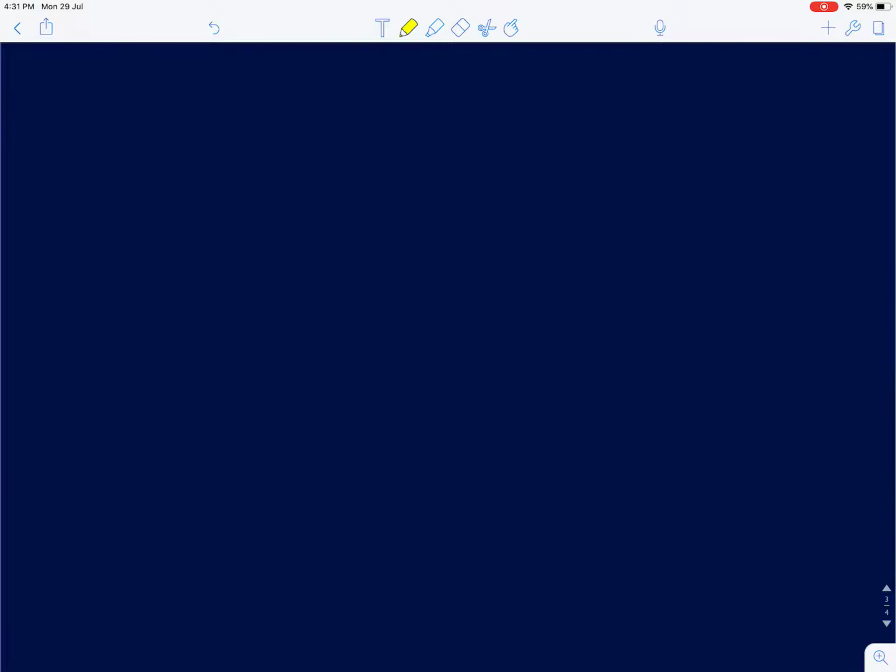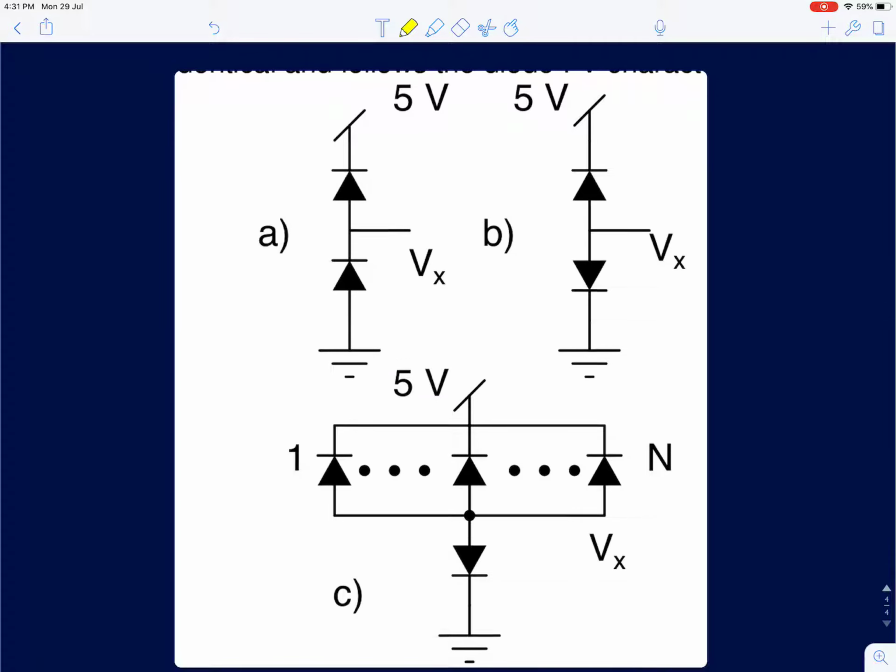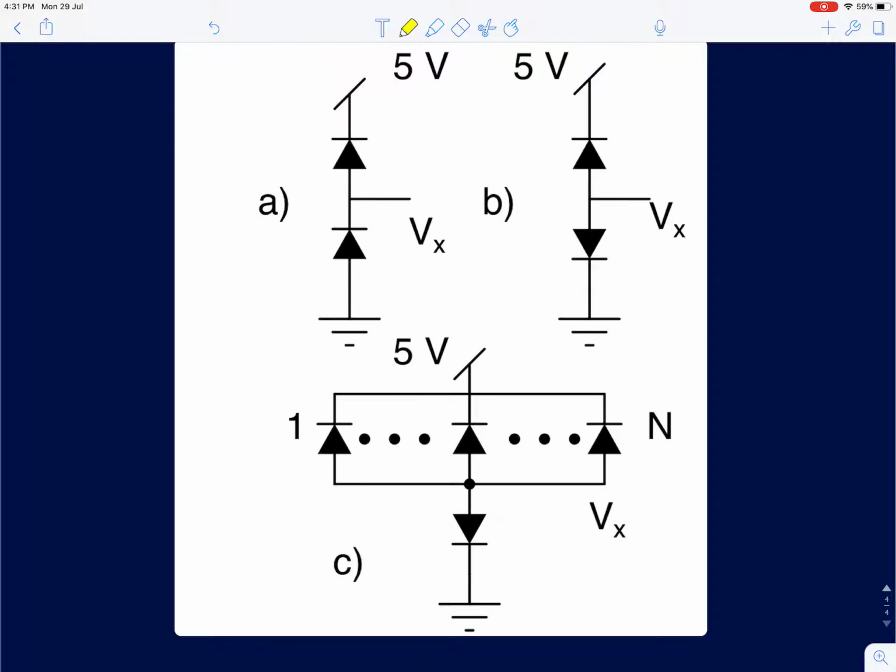So with this I'll discuss a few problems in diodes. You are supposed to analyze these three circuits and find the voltage Vx at each node shown here in this circuit, here and here. All are assumed to be identical diodes. I'll introduce a term called cut-in voltage very soon. The voltage required to forward bias a diode is much smaller than 5 volts in this example.